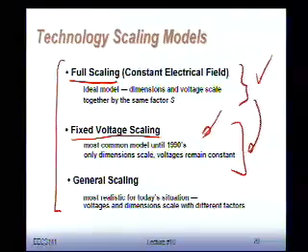At 0.65 volt, you keep on scaling your thresholds lower and lower. Remember that leakage thingy? Your leakage goes through the roof and the power goes up again. So today we're kind of waffling. We're in waffle mode, basically. Nobody really knows what's going to happen with supply voltages in the years to come. Some people say they still have to scale. Other people say, no, we're not going to change them anymore. So that's the two extreme scaling models.